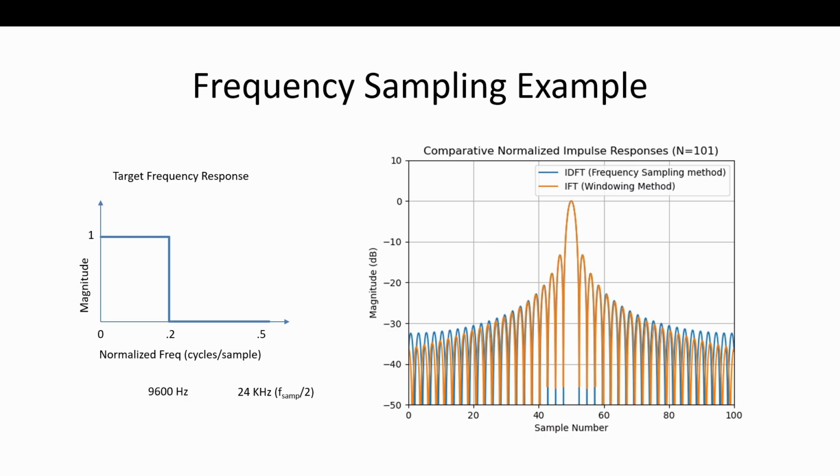And a way to picture it is, I told you about our perfect sinc going down, and it keeps going down, right? So what's going on beyond here? What's going on beyond there? If there's aliasing, it's folding back. And you see it. So this energy that's just beyond there folded back and raised it up, and that's why that's higher. So this error is due to that aliasing.